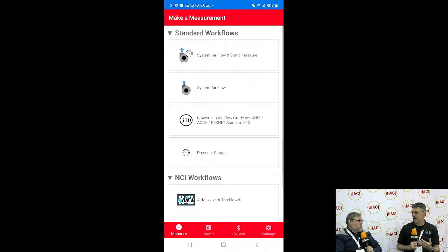And something new they brought out within the past month is system forecasting. So you can take the readings off the TrueFlow Grid and say you might want to be putting in different equipment. You're converting from gas to a heat pump. Right, so our airflows can change. The airflow is likely going to change because heat pumps typically need more airflow per BTU than a gas furnace does. Yeah, well, as much sensible as we can get out of the system. Right. So you can now use this tool as a sales tool or as a forecasting tool to say, hey, I can fit this heat pump.